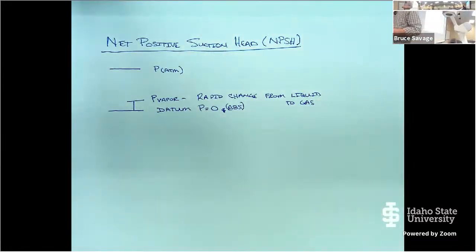As we pull fluid away, we're actually creating a negative pressure because pressure and velocity are inversely related. High velocity, low pressure, right? Like when we go through a Venturi meter, you speed up the velocity so you get low pressure. So here, when we're pulling the fluid away, we get extremely high velocities because we're moving it really fast, and the low pressure is on the back side.